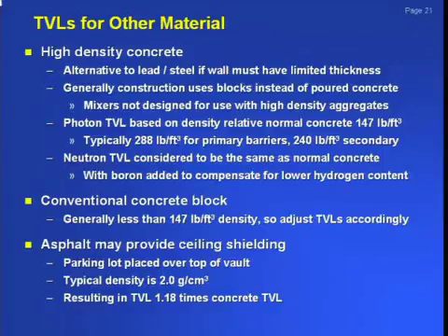The construction blocks that are used are usually already poured concrete, so you can pretty well count that they have verified that their concrete meets it. Ask them for test specifications for that particular run of concrete block. I have been burned more times than I really want to know about on contractors shorting or basically pouring lightweight concrete. That is probably the number one problem you have, not getting your concrete of the proper density. Conventional concrete block is specified at 147 pounds per cubic foot, so adjust your TVLs accordingly.